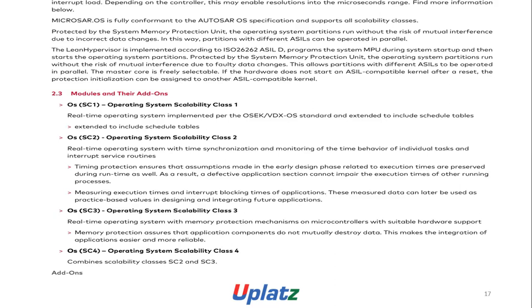MICROSAR OS is fully conformant to the AUTOSAR OS specifications of all scalability classes. Protected by the system memory protection unit, the operating system partitions run without the risk of mutual interference due to incorrect data changes. In this way, partitions with different ASILs can be operated in parallel.